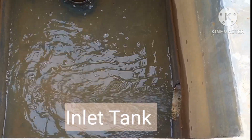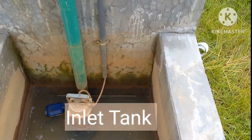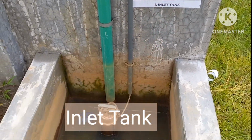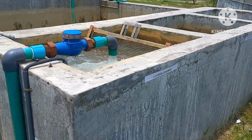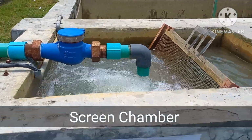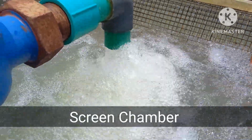This is our inlet tank, where the wastewater comes out from the production unit. Through a pump, this wastewater flows to a screen chamber. This screen chamber is made of MS with an opening of 25 mm square.